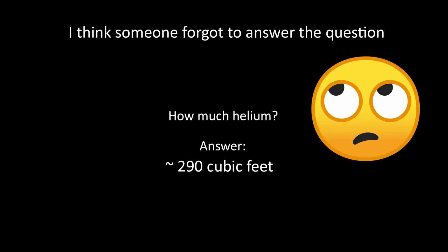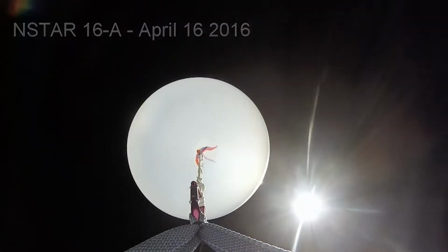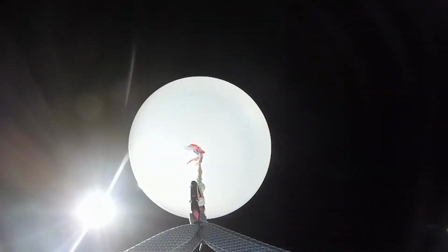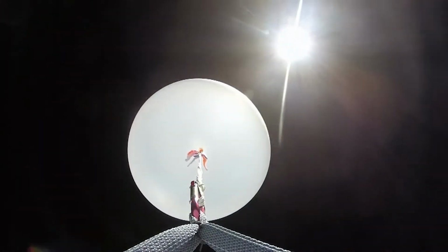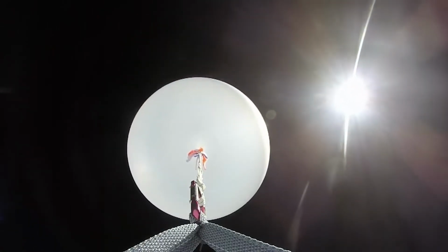How much helium? Well, we were hoping to achieve the same altitude that the National Weather Service does with their balloons and try to make it to 100,000 feet. I don't believe any of my flights ever made it to 100,000. I think most of them ended up in the 90-some thousand feet range, but still up there a ways. And the amount of helium you put in also dictates the ascent rate. We always tried to make it around 1,000 feet per minute. And that way it took about an hour and a half or 90 minutes to get to burst altitude.